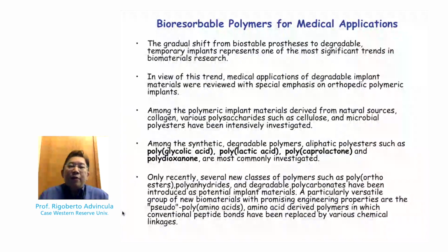So talking about bioresorbable polymers, they are good for devices, prosthesis devices that degrade over time. And in biomedical engineering, there's a lot of interest in this, or even 3D printing, because let's say with 3D printing, one can create scaffolds that will allow the formation of, let's say, tissues or bone of specific shapes or sizes.